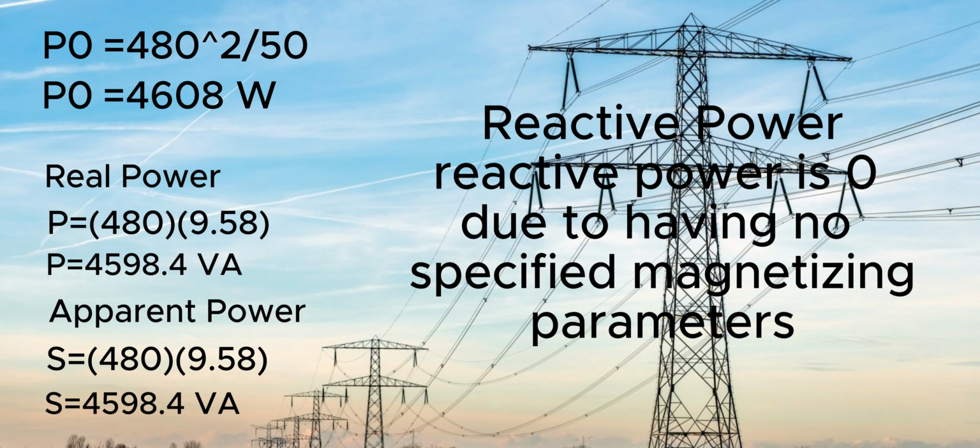We learned that this test is primarily used to determine the transformer's core or iron loss and magnetizing current. Since the current drawn under no-load condition is relatively small and the copper losses are considered negligible, overall this activity demonstrated how open circuit testing can be used to evaluate the efficiency and operating characteristics of a transformer without connecting a load.